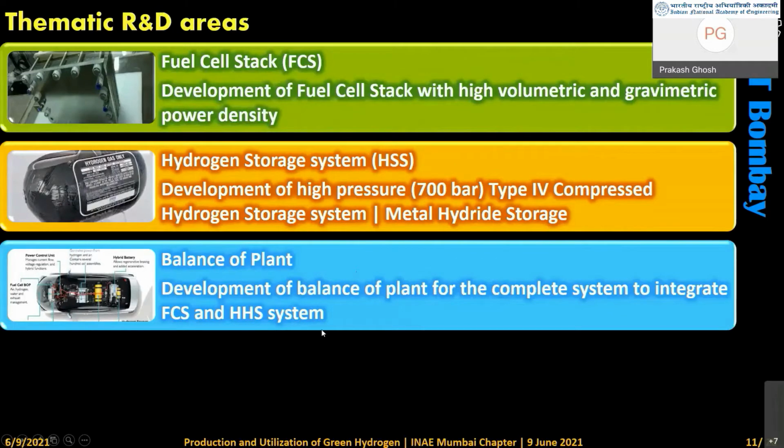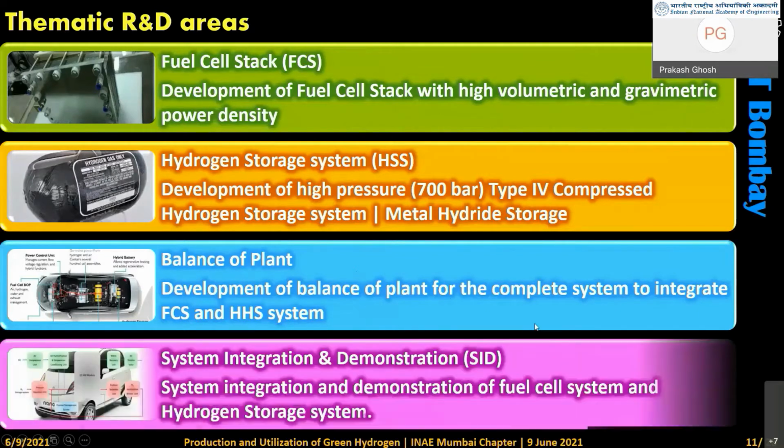And I wanted to mention, because we are struggling now, because we have the fuel cell stack at least ready for 5 kilowatt. But we need to test it, and we are always trying not with oxygen, always we are trying with air. So we need to have an air blower. And to buy this air blower is very difficult. We are not getting it in India. So even designing the balance of plant is also very important. And finally, the system integration is the next component.